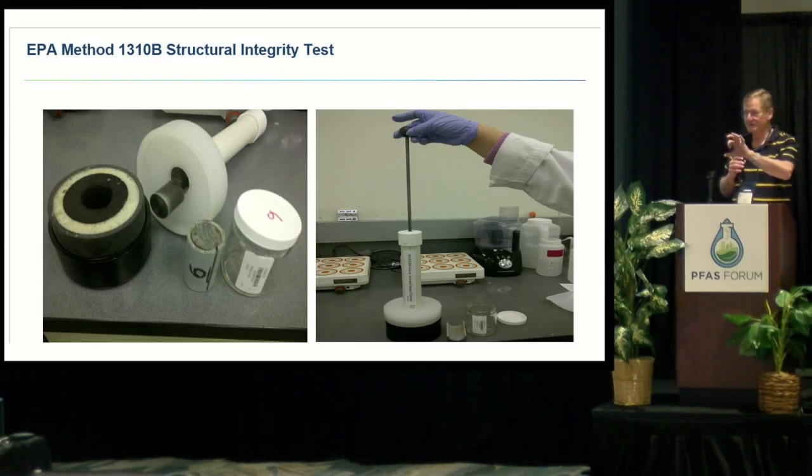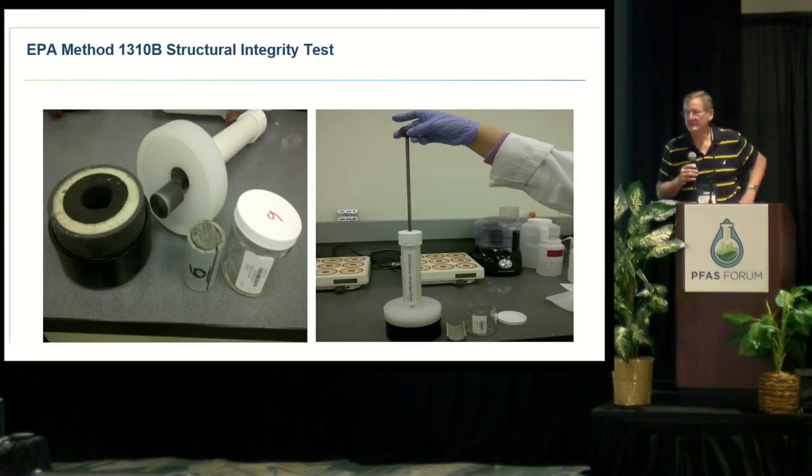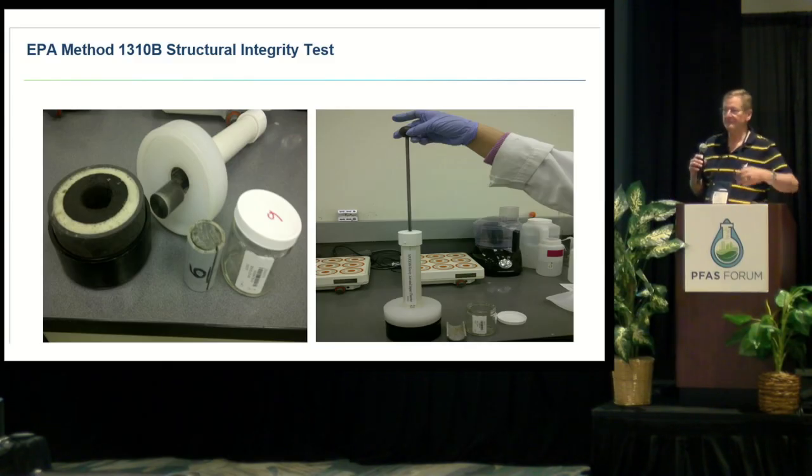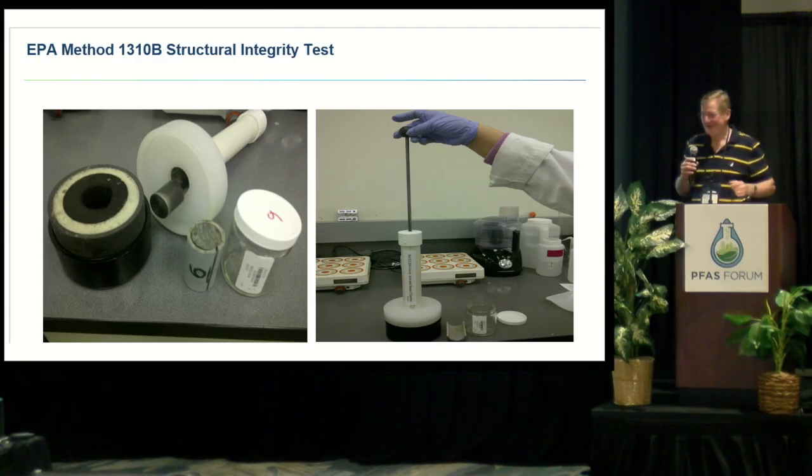This is about as close as I could find, and multiple states and EPA have accepted my data from this process that I'm about to describe. It's a little cylinder. It's about 7 centimeters tall, about 3 centimeters across. It has about 80 square centimeters of surface area, and that's going to represent my full face of the landfill for that course of the day.